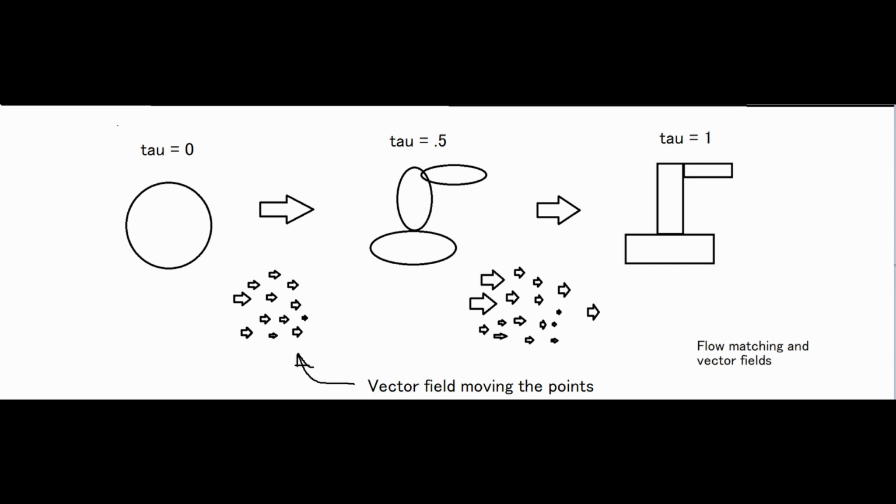To do this practically, first sample a time step tau. Since our target distribution here is the distribution of action chunks, to set up the linear probability path, we just need to take the ground truth action chunk from our data set and then interpolate it with a Gaussian at that time step.